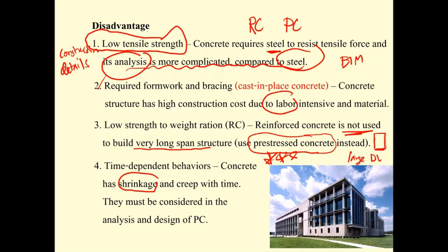And another thing is creep. As we may know, the concrete contains water inside it. If your structure gets forces all the time, the wall is going to get closer and closer, right? When it has the force like this, and it gets shortened, the water in the air voids is going to come out and evaporate.